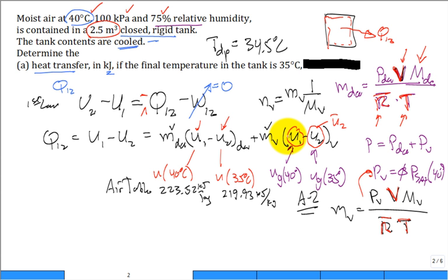Maybe I should check it myself. Here, I'll check real fast. I don't want to say something wrong. Yes, the saturated liquid's internal energy is set to 0 for steam. So that's the starting measuring point for energy in table A2. What about A22?